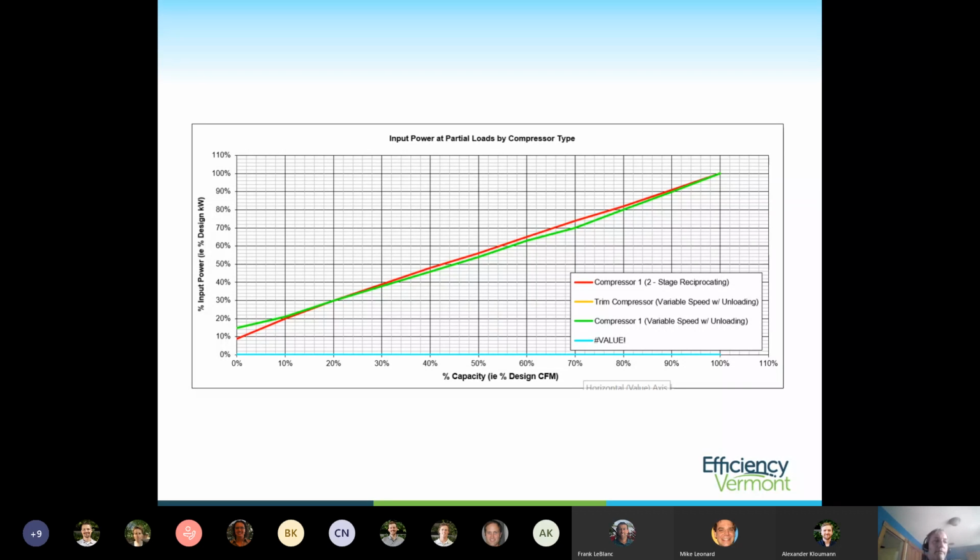The reason why reciprocating compressors are dominant in about the 25 horsepower and less, but the rotary screw is hitting the larger market, is that a reciprocating compressor, although it's efficient, can be very loud and produce vibration. As you get larger and larger reciprocating compressors, you get louder and louder systems, and you have a lot of vibration, and you end up having to engineer a footing to hold that compressor down so it doesn't vibrate the whole site.